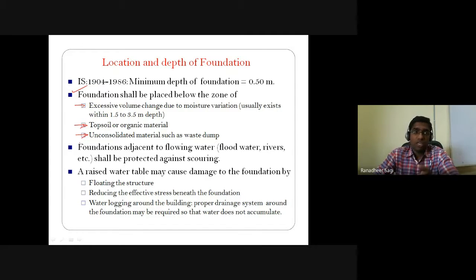Let's say the region where you wanted to take up the construction was a low-lying area where the soil got deposited, or municipal solid waste deposits were filling that region, where the process of consolidation in that soil deposit is not completed, or the complete decomposition of the material didn't happen by the time you went on to construct the foundation there.